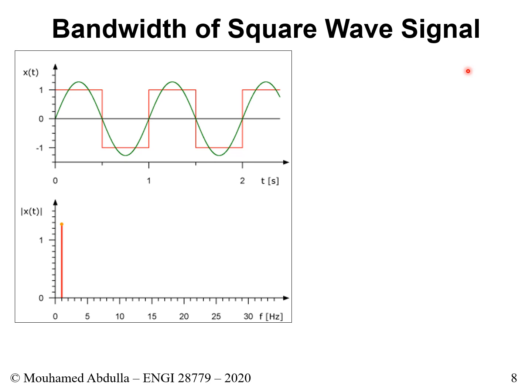Then we took that result and we looked at the Fourier series representation of the square wave signal in the frequency domain. Now that we moved to the frequency domain and we're able to see the square wave signal there, what are the key things that we could extract? One big and critical item that we're able to detect, to measure, and to assess is the bandwidth of a signal. The bandwidth of a signal is best seen, best detected and best understood in the frequency domain, not in the time domain.